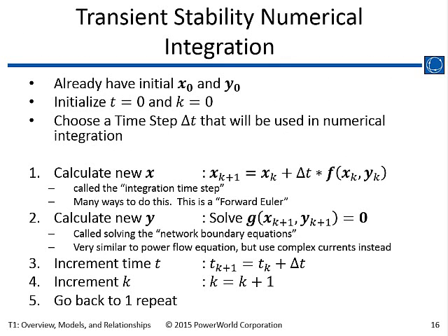What we start out with is you get your initial conditions, you set some initial time, and usually time is set to be equal to 0. You have to choose a step size, which is going to say how fast you are integrating your differential equations. By edict, WECC uses a quarter cycle time step.